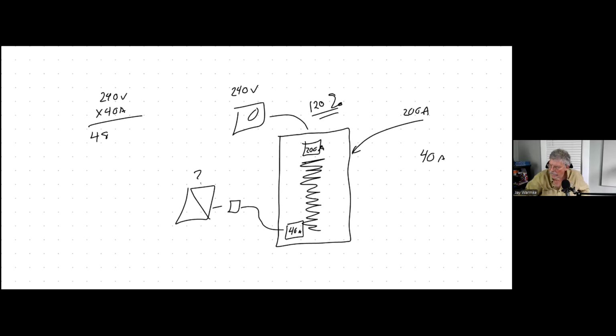This is terrible that I can't even remember that. 9,600, 9,600. All right. So we would get 9,600 watts. So you might make the mistake of saying, okay, we can have a 9.6 kW inverter, but that's not right. Why? It's because the National Electrical Code says we always have to have a factor of 1.25 safety margin for